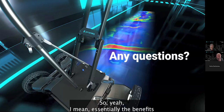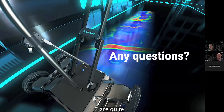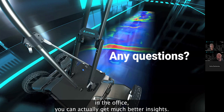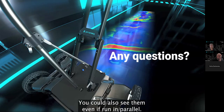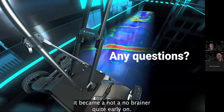So essentially, the benefits of a second polarization in a low frequency antenna are quite negligible in reality. Because with a reconstruction in the office, you can actually get much better insights. The things that you would miss are the same, and the things that you could see most likely with an antenna spacing of 7.5 centimeters, you could also see even if running parallel. And essentially, in that trade-off, it became a no-brainer quite early on.